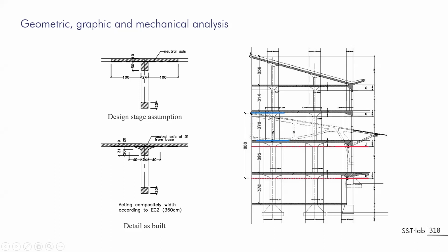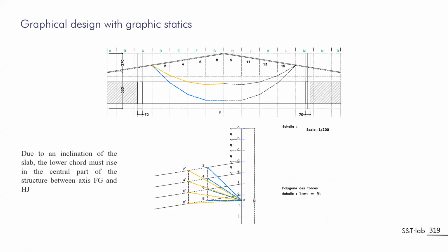And we see that the dividing struts will be half of the span you have between two columns. So you have a kind of graphical system in which you have to place yourself to design a structure. So first you want to draw a funicular line. You would like to have a funicular line that would be horizontal in the middle. And if you do so, you have to have in mind that this funicular line will be equivalent to these two lines of the roof. So you are building a load line in which, from the corresponding letter, you draw a parallel to the roof. And you have to connect to the rays that will give you the geometry of the funicular line.